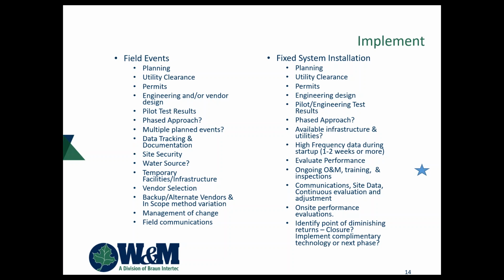I've seen and been around a lot of systems that were underperforming for a few different reasons. Some of it correctable, some of it they missed a boundary condition and probably should have added some more wells or augmented with a little bit different technology. But one of the most common things that I see in underperforming remediation is the level of training and experience that goes in to the operations and maintenance.